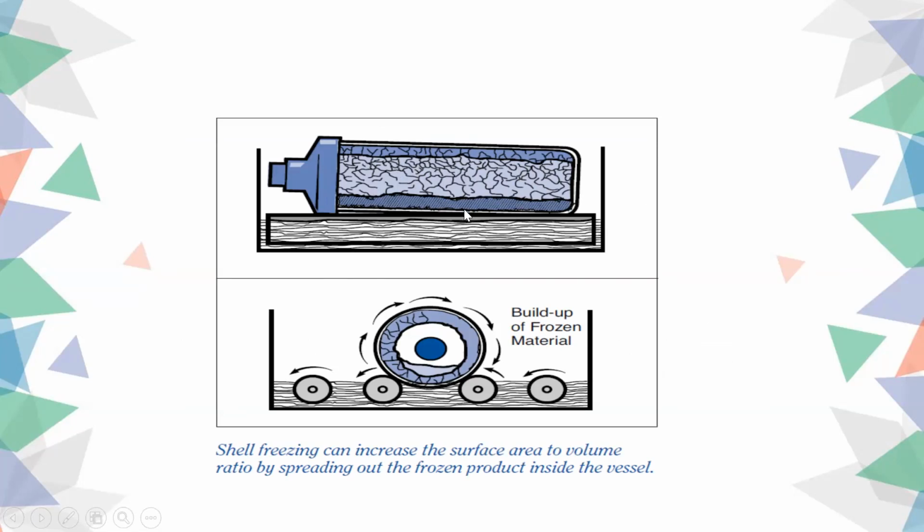So the three steps that can be used to speed the freeze drying process, or reduce the time required, are choosing a freeze dryer that has a heat source such as room temperature, knowing the eutectic temperature of your sample, and increasing the surface area of the sample.